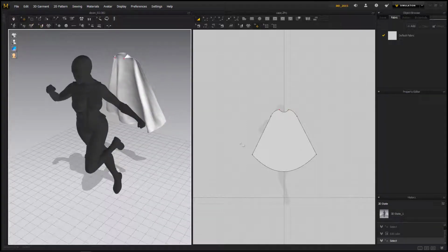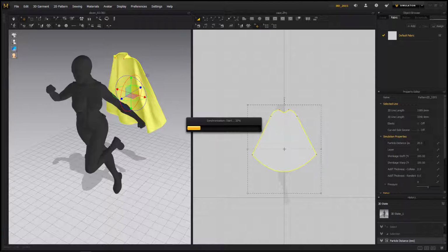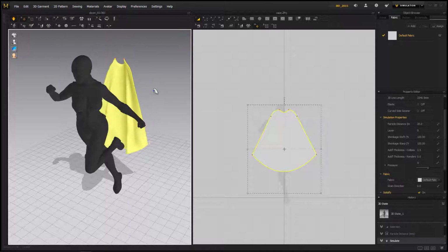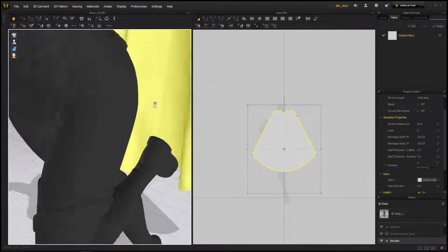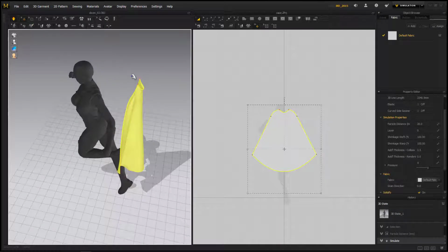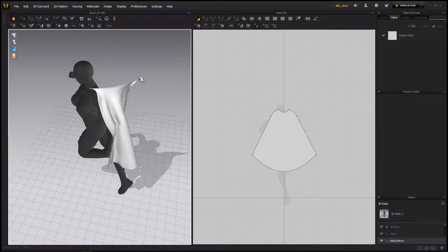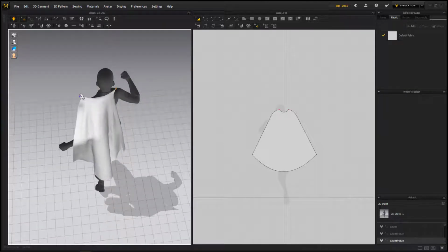And those pins that I have there, well, first of all, particle distance, I'm going to set it to 20 for now, because otherwise it's going to be too heavy. I need to experiment a little bit. So if I simulate, there it is, it falls like there. There are 2 pins at the top that keep the cape in place. So I'm gonna need to move these pins into their new location, which is gonna be one, it's kind of there,